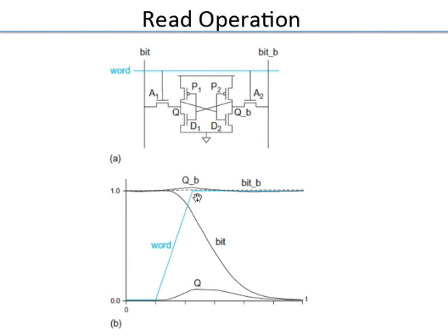Now one important thing you notice out here is that as the bit line starts discharging, you see the voltage at node Q goes up a little bit. There's a small bump. Why? Because if you have to support any current, you need to have a VDS in this transistor D1. Remember, Q is 0. That means input to D1 is high. That is, Q bar is high. So VDD is here. So this is on. But if I want to have any current, VDS has to become bigger than 0. The other way of looking at it is, if you have any current, I times R, there is some voltage drop.